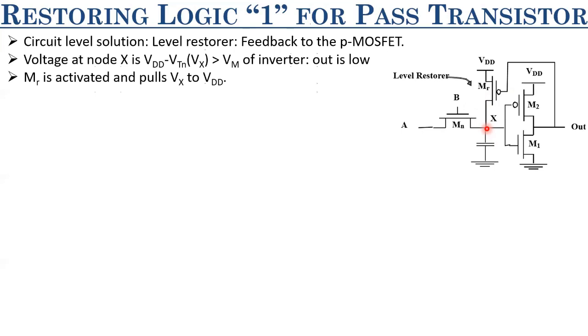However, as I told, there's no free lunch in VLSI. There has to be a trade-off. So what is the trade-off here? Before discussing that trade-off, let us talk about the static current path. Here, if you look at the circuit, there's no static current path between VDD and ground. I mean, VDD and ground are not ever connected through a MOSFET which is not in the cutoff mode, right? So that way, even static leakage paths are minimized. So static power dissipation is minimized.